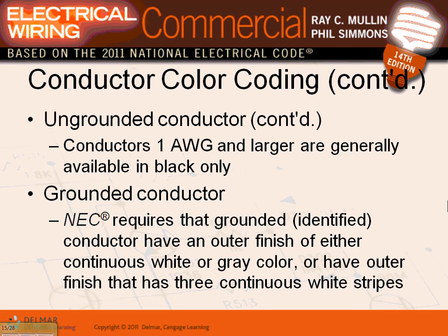You have to. If I'm using this one as a grounded conductor, and I'm using 208/120, for example, I can put a white tape around this conductor at every location where I have access to it: in a J box, inside the panel, where it lands with the equipment. I don't have to cut through the conduit here to tape it. Just where I have access to it. Wherever I have access to it, you can tape it with white.